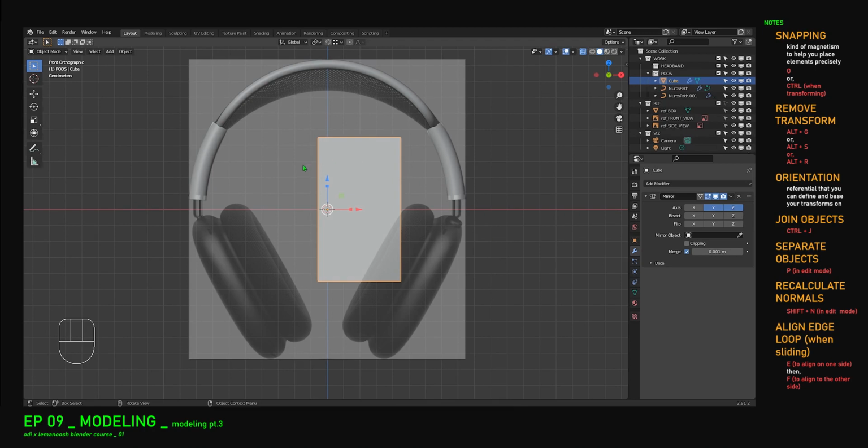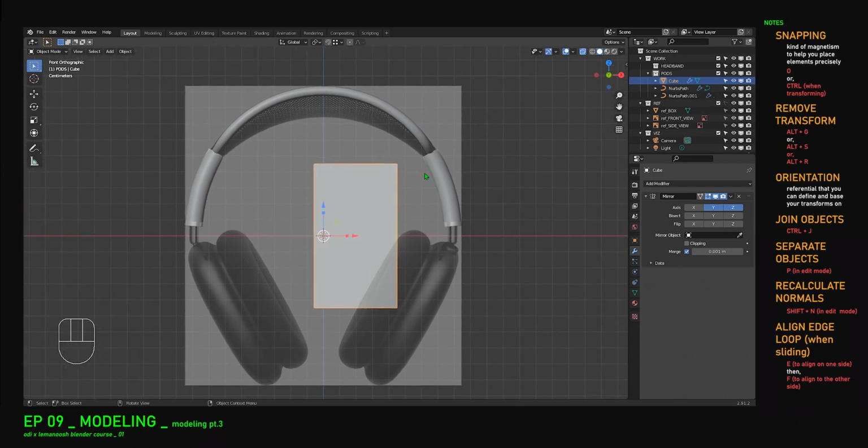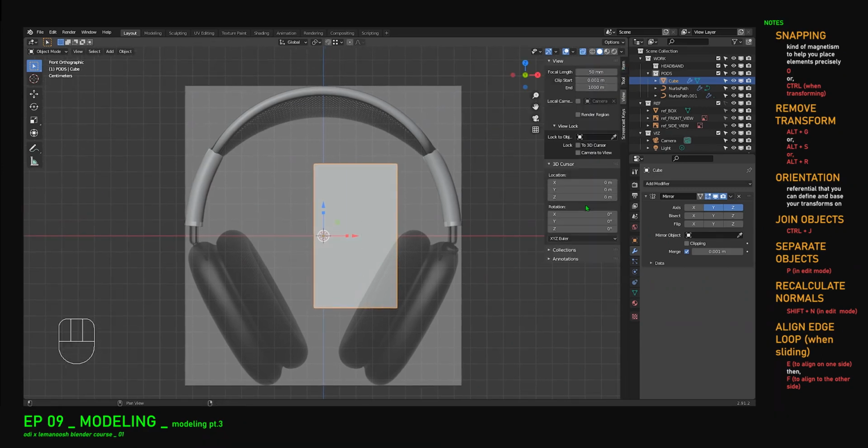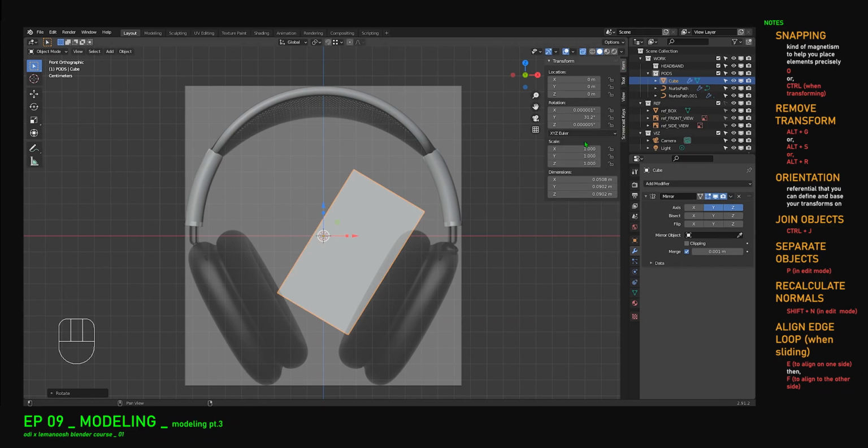And you remember when I told you that we don't want to scale or rotate directly in object mode most of the time? This is because the rotation can be a super precious value. Like if you rotate here, and we go in item, not in view, you can see that I have my rotation angle here, and this means that I can revert it at any time. So here, if I try to match with the rotation of the thing, we can say that I'm around 28 degrees.